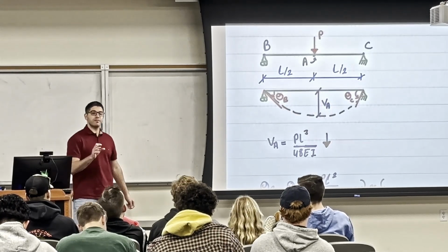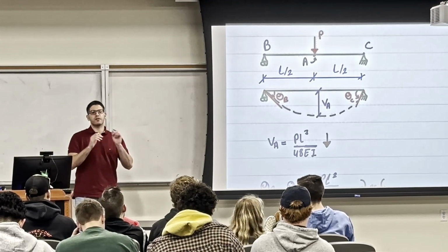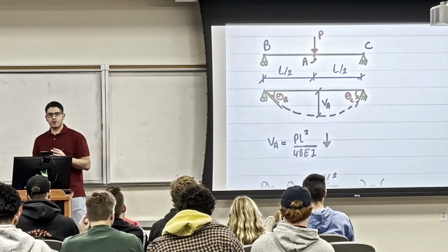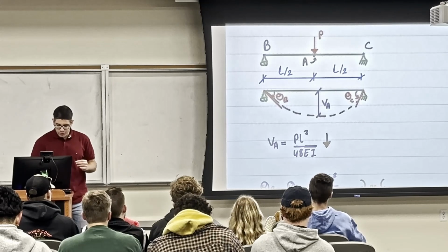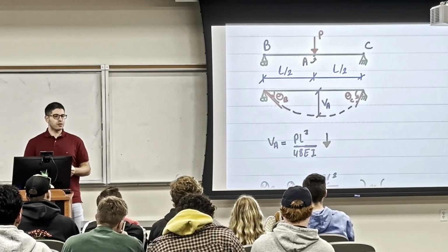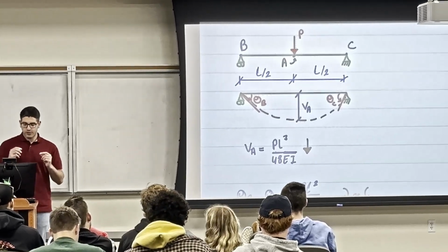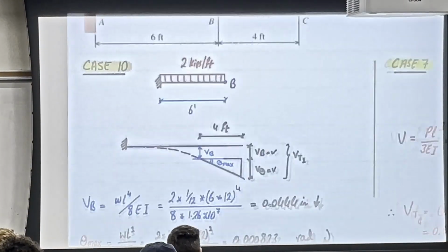So no, the curves in the table are not an approximation. The equations, you're going to develop them in advanced classes. All this conjugate beam method, moment method, you're going to develop it. So the point is, when you do the trig, at the very first point here, you are estimating a very big deflection that's not real. That's why we only do trig at a location, for example, like what we did in this example here.